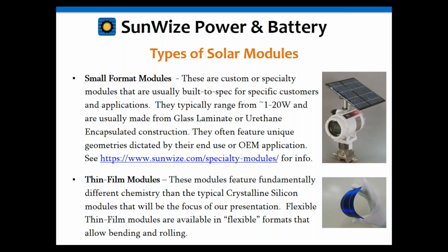The idea behind the amorphous is it can be made flexible. Backpackers use a lot of those, because they can roll up and stick in their backpacks. The negative is that they are about half the efficiency of a regular solar module, so you need twice as much area, and sometimes that can be a problem. So a lot of people generally go for the crystalline unless there's a specific need for the thin film and the amorphous.